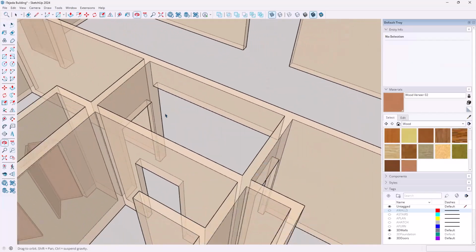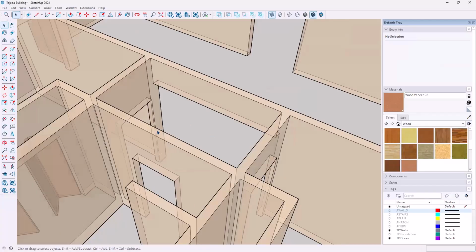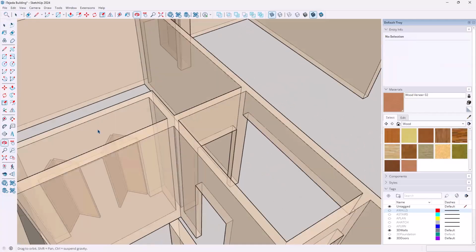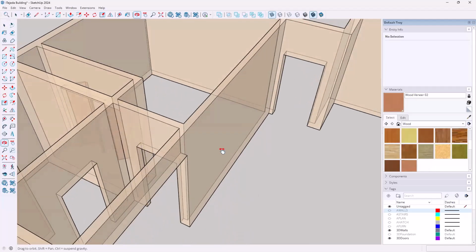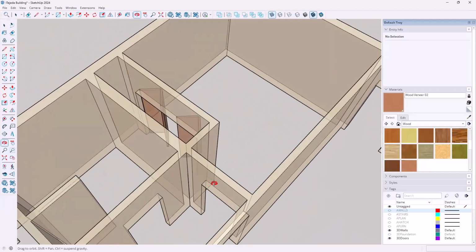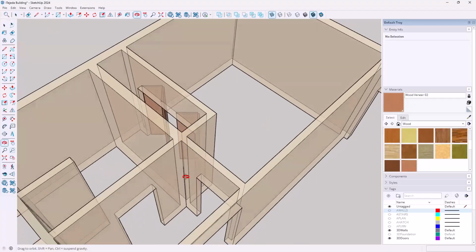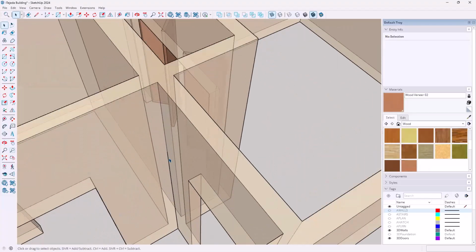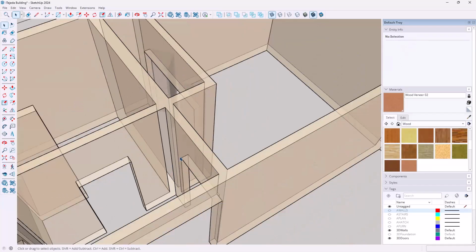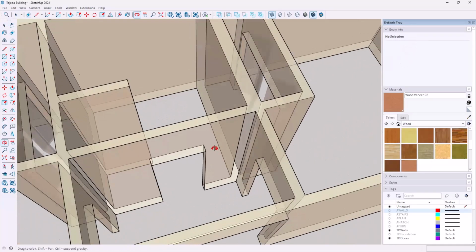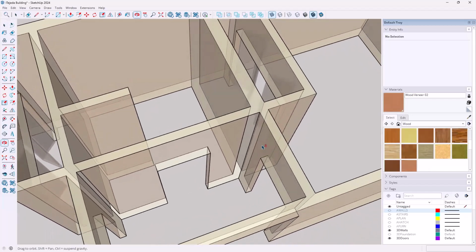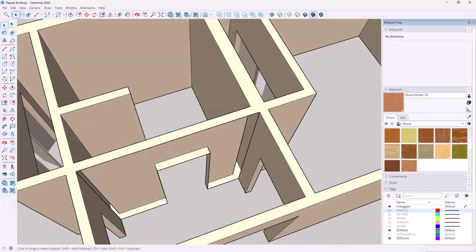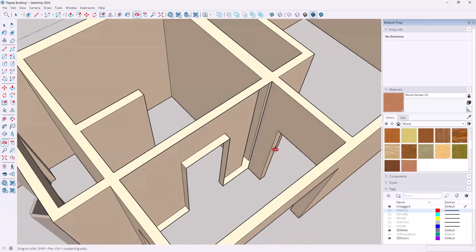And I'm pretty sure that something I did here is affecting that. For all I know, there could even be a double line somewhere that's creating the problem. And as I look around, you see that? You see this? There seems to be like a line, extra line right here. If I click one time, you see that? If I delete it, see how it's deleting that whole surface? So something interesting is going on here that I need to resolve.